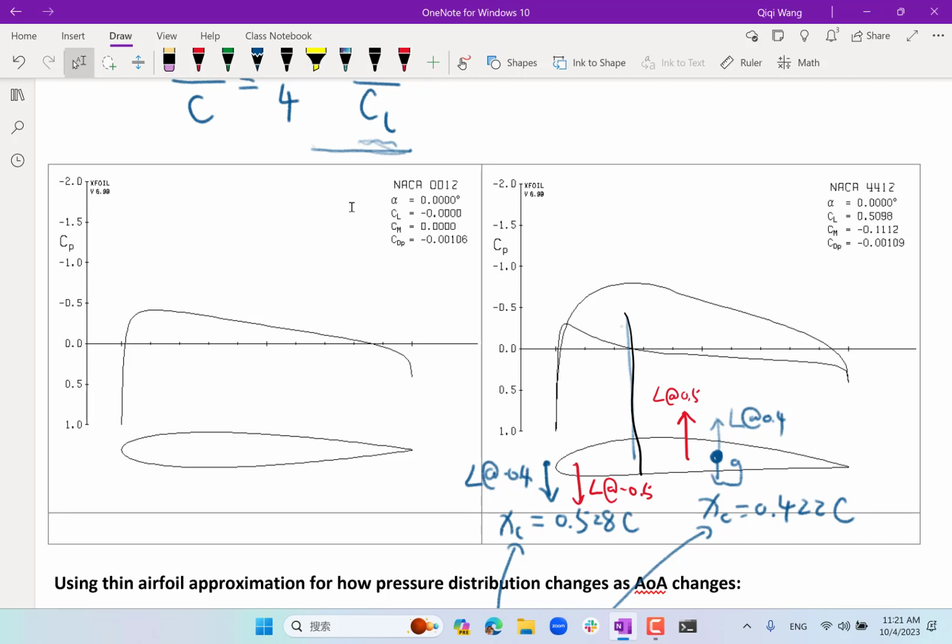so that the nose actually goes up, right? And the tail goes down in this frame of reference. That's actually increasing the angle of attack back towards 0, and restore the airplane to a lift coefficient that is closer to 0.